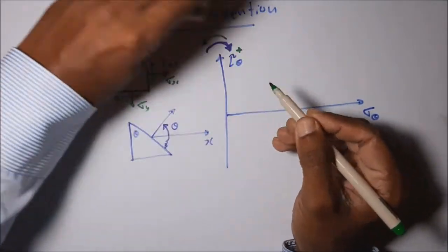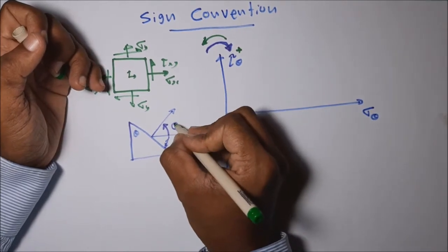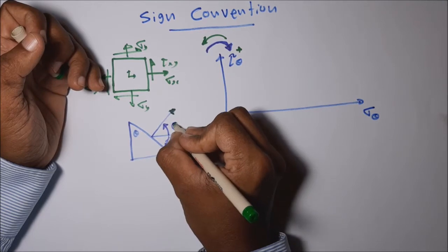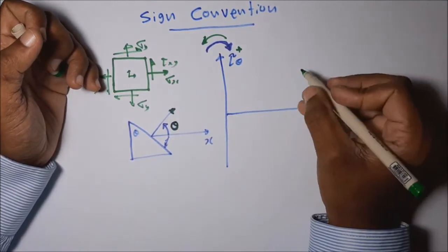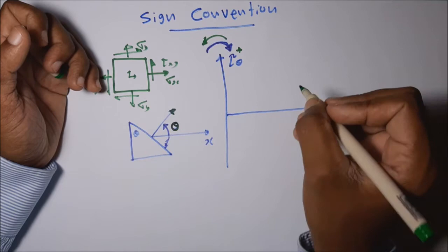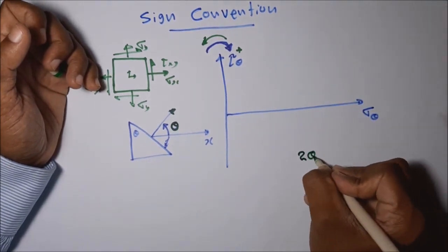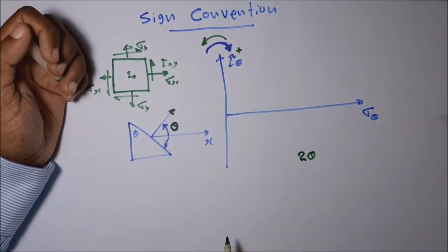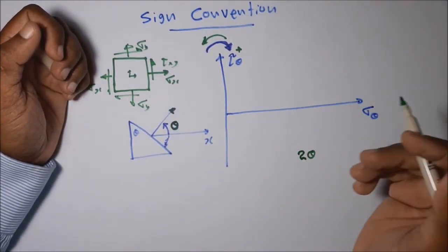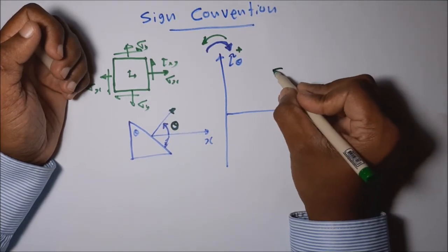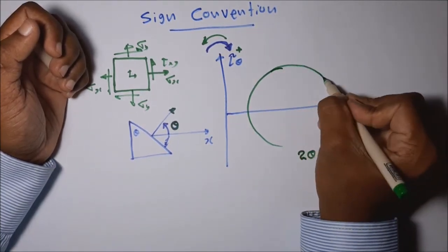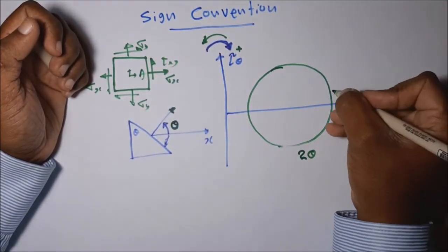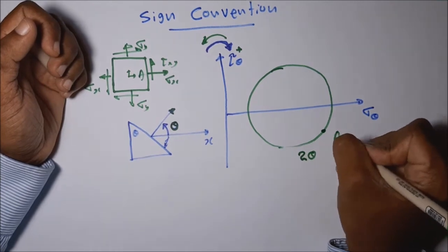Another important thing is, when measuring on the two-dimensional planar stress diagram, if we take a certain angle as theta, in a Mohr circle diagram it is represented by double, 2 theta. If we take a certain angle as theta, it is represented on a Mohr circle diagram as the double value. Okay, for example, let's take a certain point A.